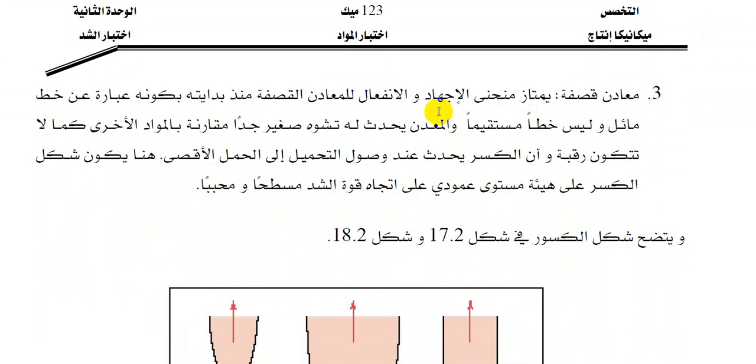3. Brittle materials. The stress-strain curve for the brittle materials is characterized from the beginning by an oblique line, or an inclined line, and that is aligned, as you can see here. The metals will experience very small deformations as compared to the ductile materials, there will be no necking, and the fracture will actually take place when the loading reaches the maximum limit.